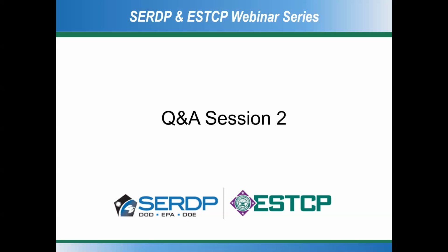Thank you. And this is a question from the University of Rostock, all the way in Germany. Does the dynamic seabed burial model analysis assume full liquefaction of the seabed sediment? So that's a great question. The initial iteration of the model that we worked with did assume full liquefaction, and we have now progressed to a second version of the model that allows for a degree of liquefaction. So no, where we are with our work right now, we do not require the bed to be fully liquefied to see partial burial or some burial happen.